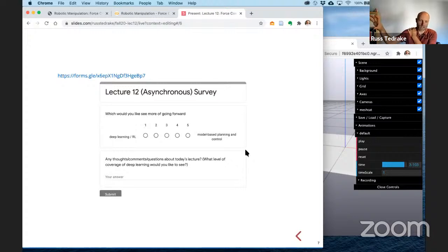So the floating hand assumption, the reason I'm okay simulating floating hands is because we can actually make that true. You have to do your due diligence to understand how to get there and what the limitations of those controllers are. But roughly speaking, we can impose dynamics on the hand. And so the interesting thing then becomes the dynamics between the hand and the world, and the contact forces and grasp planning or non-prehensile manipulation.